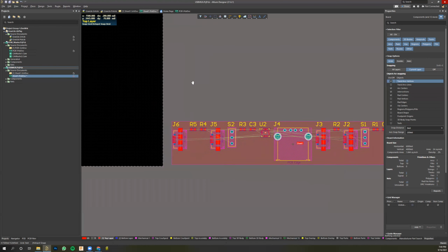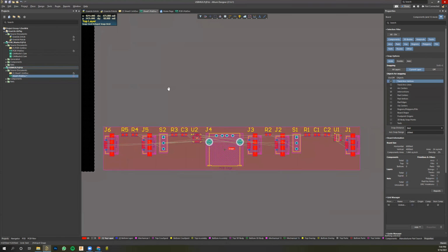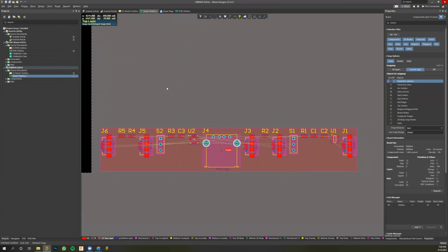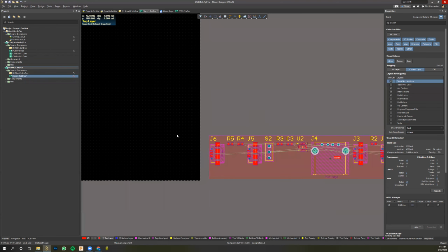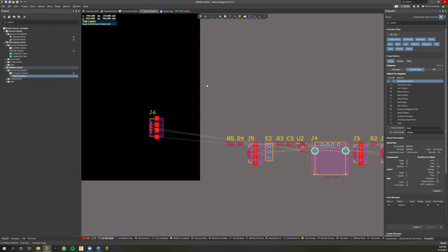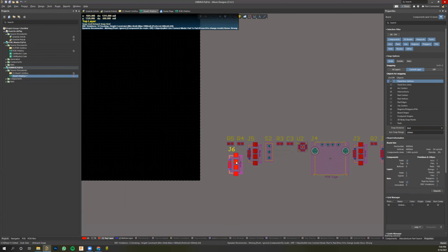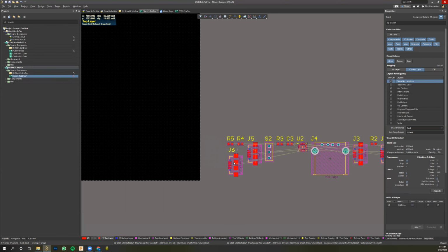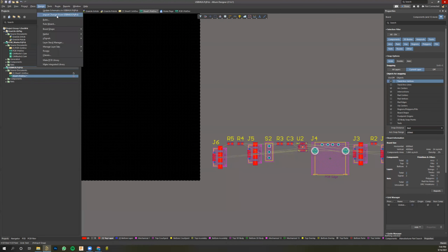And it's really just an organizational thing, as far as I can tell, to help, especially if I have more than one schematic page, it becomes obvious. But the annoying thing about it is if I take anything off the room, it turns green, and green is bad in Altium. And so I always just delete it. So anytime I do a design import change, I always uncheck the room because I find them irritating.